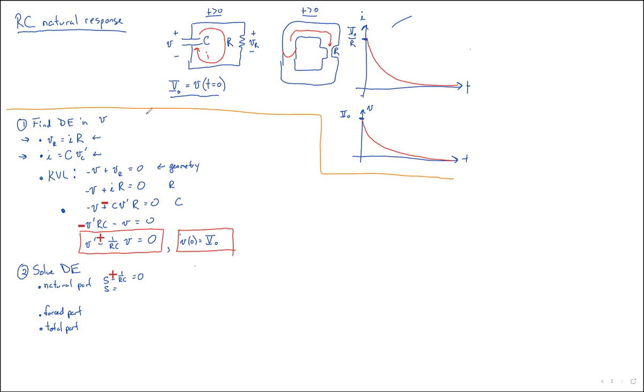And passive sign convention says, if here's your component and you've got current going into it, we always define the voltage as more positive where the current enters and more negative where it leaves. And this again is true for any component at all. This is what passive sign convention is.